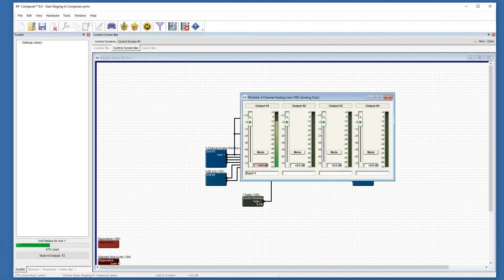Oh, I failed to mention that, of course, as we stated in the beginning in my PowerPoint, our +4 dBu value or reference is going to be right around -20. So remember that as well. So +4 dBu is right around -4 dBFS. Or I'm sorry, -20 dBFS.